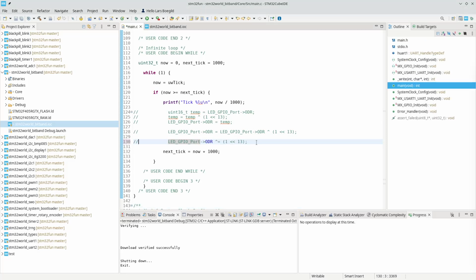And yes, there is. STM32 offers a feature called bit banding. As a matter of fact, every single byte in the RAM has a corresponding alias memory address that addresses every single bit. So every byte will have 8 other addresses that correspond to each individual bit in that byte. That is the concept known as bit banding.